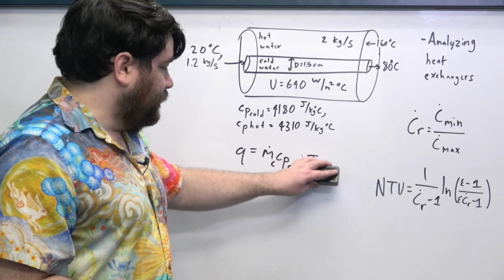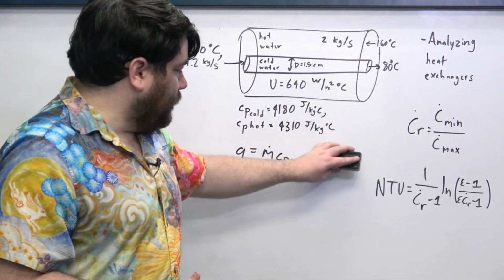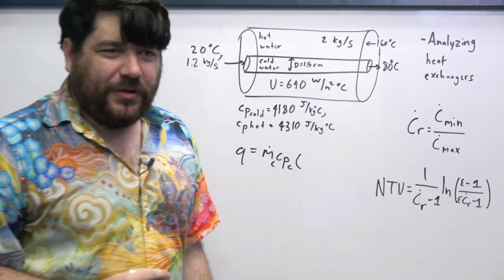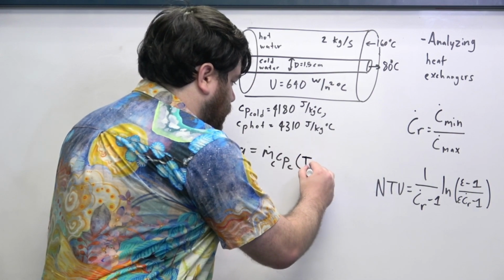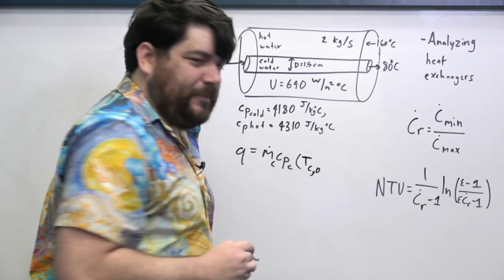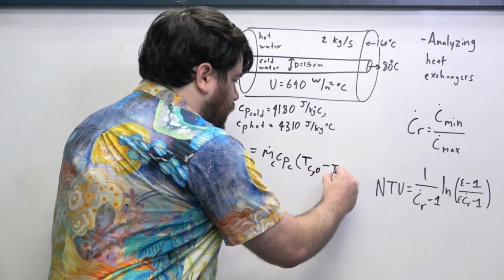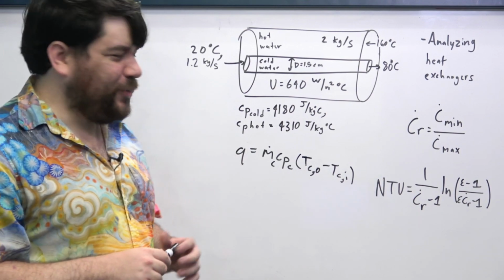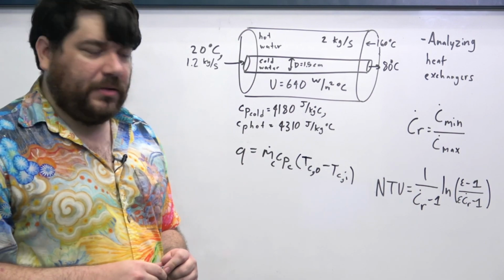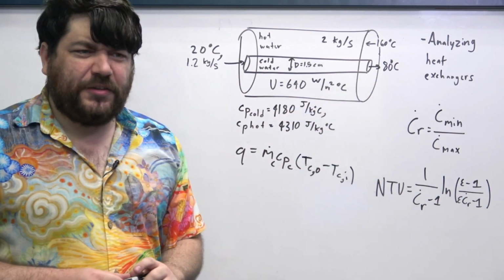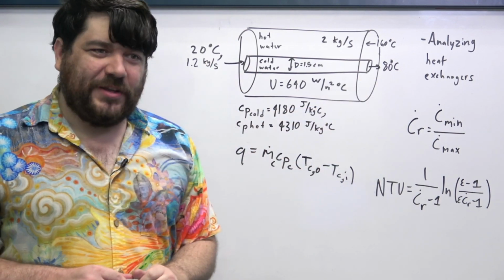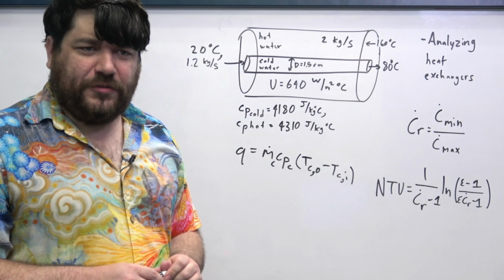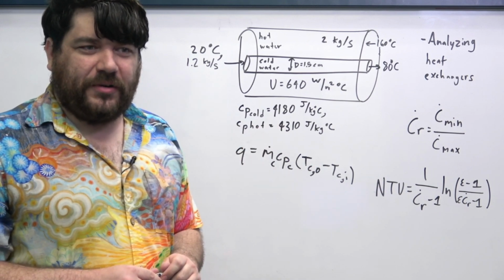and that this delta T, once again trying to make sure that we get a positive number, is just the difference in the temperature of the cold liquid at the outlet minus the temperature of the cold liquid at the inlet. Once again, this is just to make sure that we get a number that's positive. And so this is 60 degrees Celsius. This mass flow rate is 1.2 kilograms per second. And this specific heat capacity is just 4,180 joules per kilogram degree Celsius.